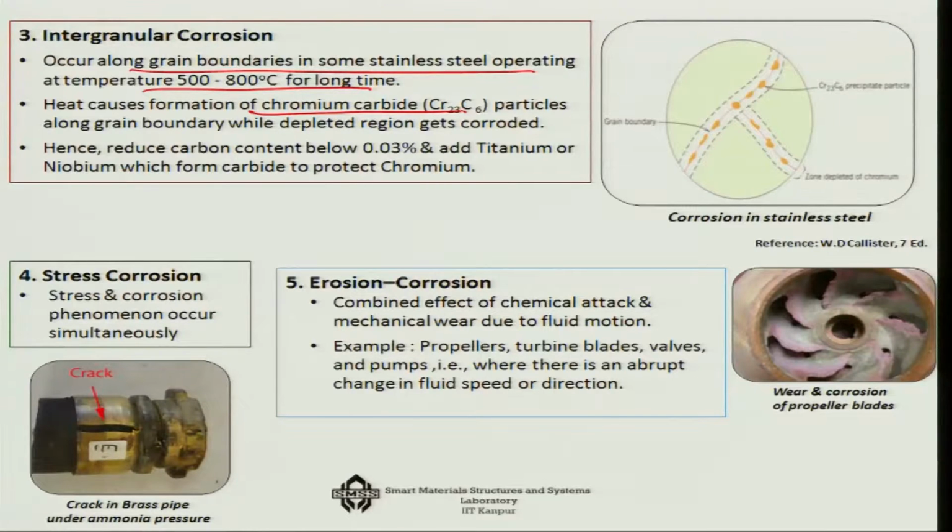Then there is stress corrosion. Stress corrosion is where you have a high level of stress as well as corrosion due to chemical reasons. Here the high stress aggravates the problem, because the material gets weaker and a larger surface is exposed, and as a result the two things help each other to increase the corrosion process.